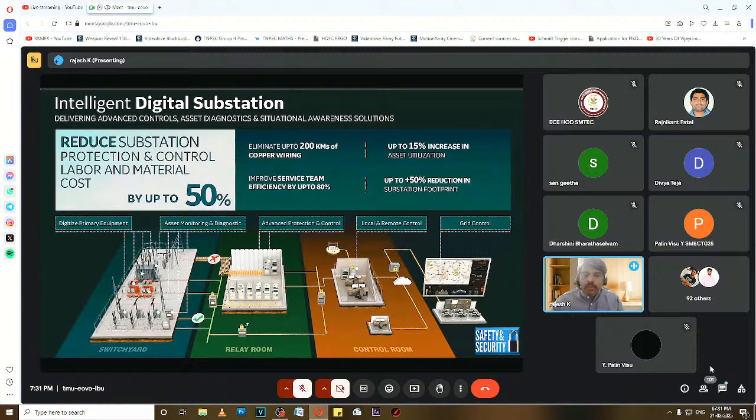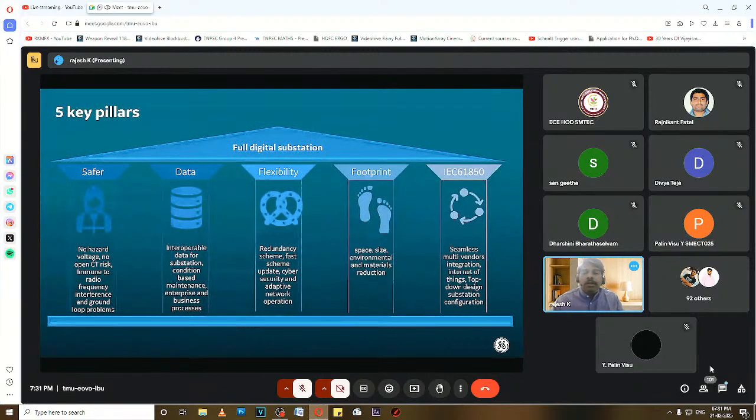So how does it work? It's all digitized using various sensors. So why do we do that? First, it's mainly for safety. It is safe because you convert everything to a lower digitized quantity right from the source. Unlike a current transformer output or a voltage transformer output, there is no risk of open circuit or a risk of 110 volts being handled, arcing in a hazardous environment.